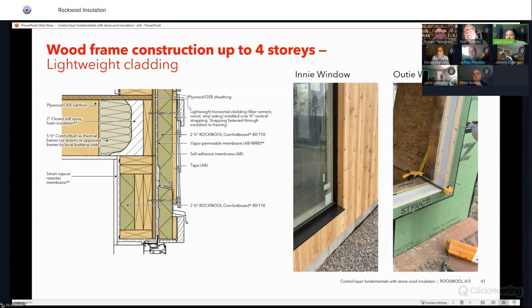So when you grab a slag wool bat, it actually is very crumbly, and that's because the slag content is higher. When the stone content is higher, it makes a better, longer fiber. So when you grab it, it doesn't tend to crumble as much on you. That's why even some of the new products are still made with slag or heavier on the slag content and considered a slag wool. So even the new stuff, when you grab it, can be pretty brittle.